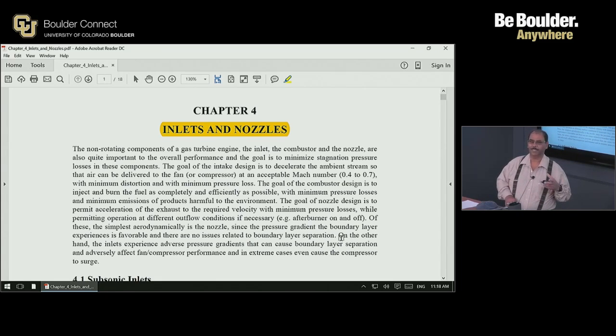But if you go to twin aisles for that range, the drag increases because the fuselage size has to increase, and the fuel economy suffers. On the other hand, if you go for a single aisle aircraft, the turnaround time increases, and that is not good.